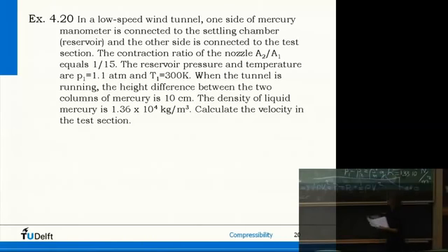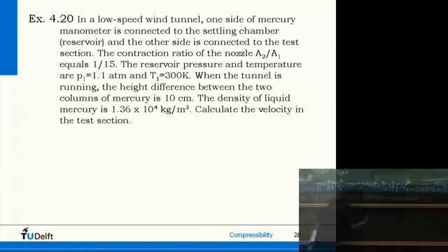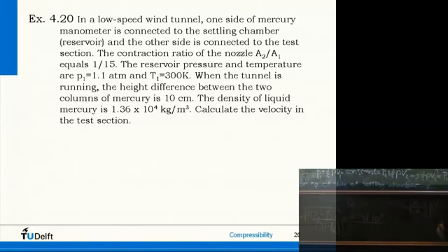Okay, so then we have the 1.33 times 10 to the power 4, that's here, the pressure difference, times 2, divided by the density. We didn't compute the density yet. So let's do the density from the equation of state. So rho is P over RT.